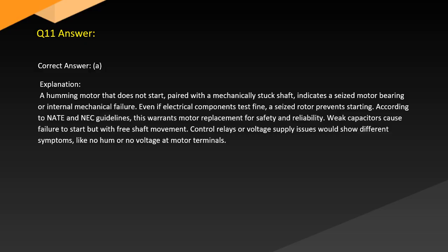Weak capacitors cause failure to start, but with free shaft movement. Control relays or voltage supply issues would show different symptoms, like no voltage at the motor terminals.